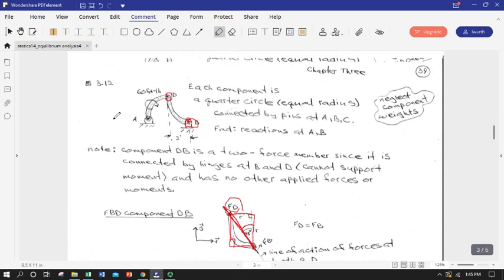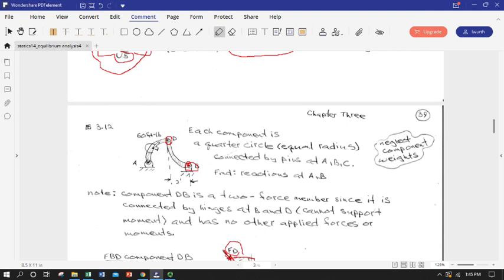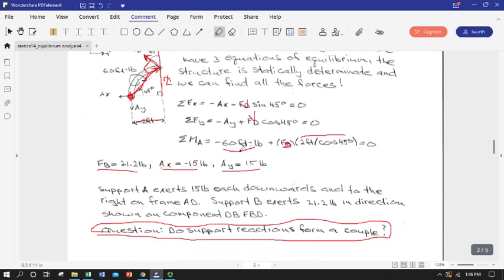And we can actually get that by going back up to the top and realizing that there are no applied forces, just an applied couple or an applied moment. So there are no external forces to balance a net force coming from the supports. So the supports have to only themselves apply a moment that opposes the 60 foot-pounds. So in reality, the sum of the forces at A plus the sum of the forces at B all have to cancel out. So in reality, A and B will function. The net combination of the support reactions will function as a couple in this case.